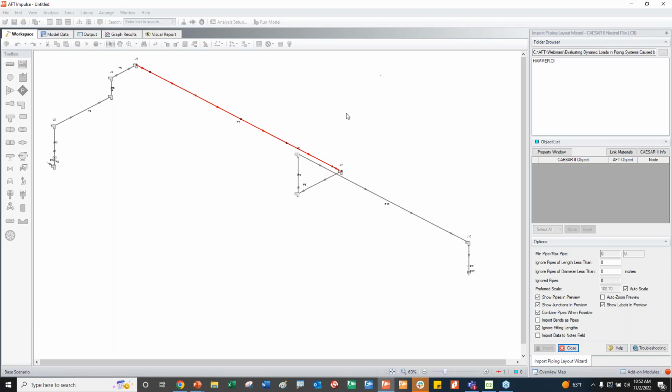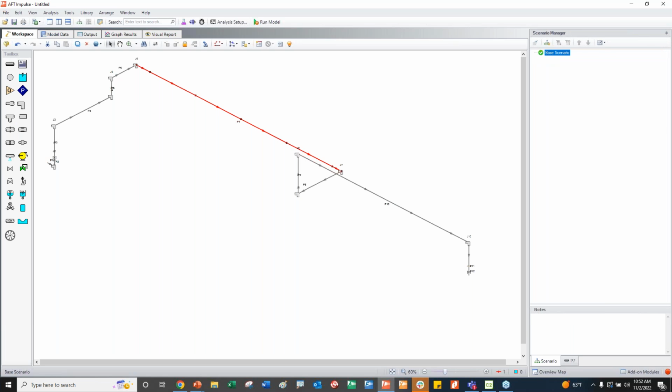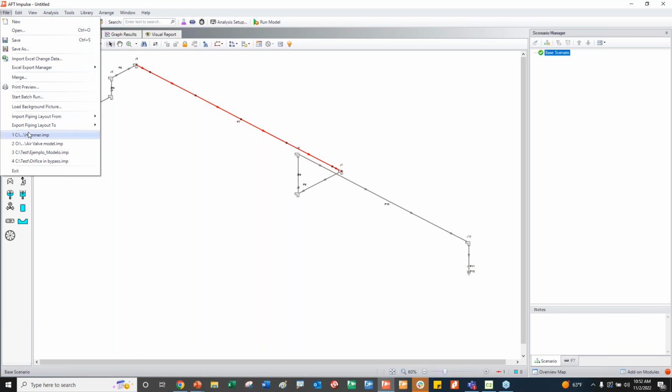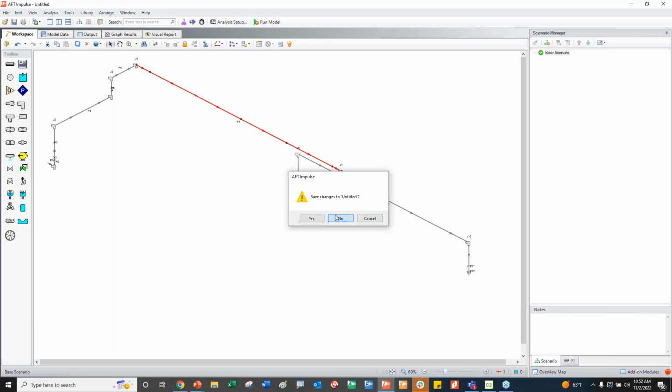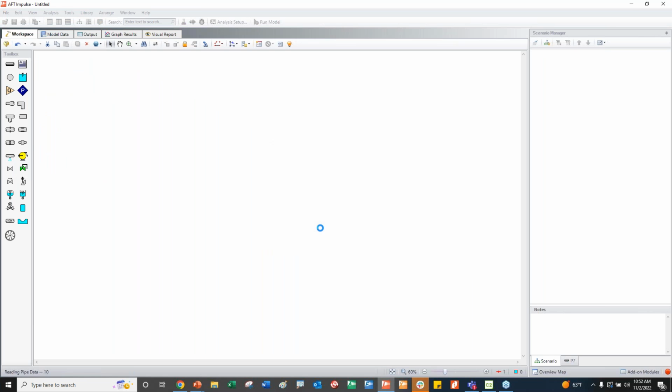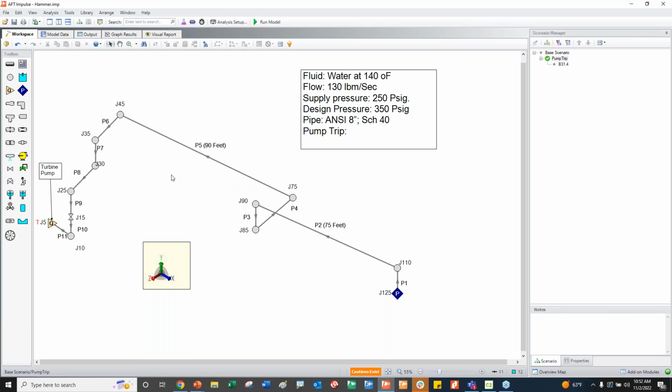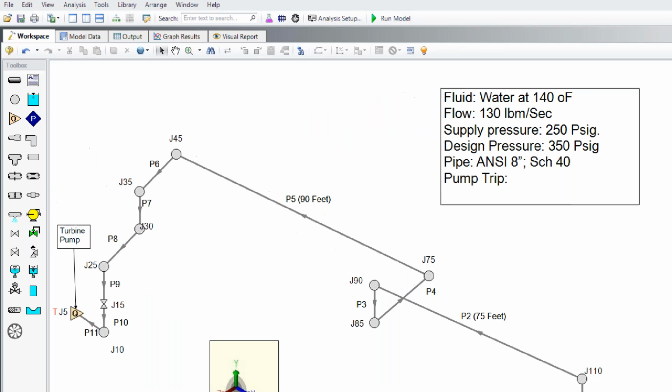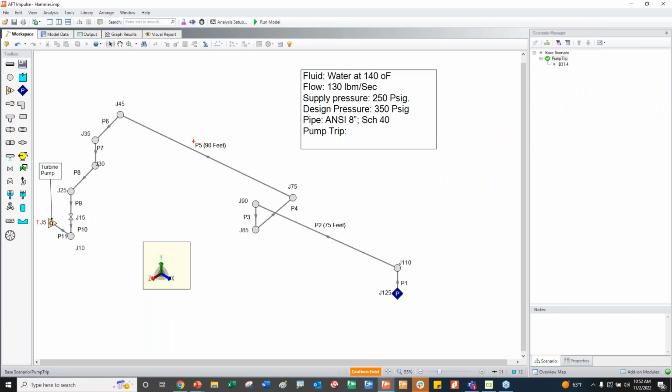Let me bring the example again. In this example, I analyzed the longest. And why? Because that's where the pressure wave lasts longer, so the imbalance force can cause more damage. This can be a pipe rack or whatever, and I want to design the directional anchors in this sense. I want to calculate it because probably we'll have to report it to the civil engineers.